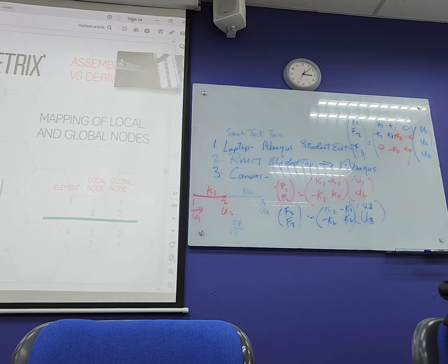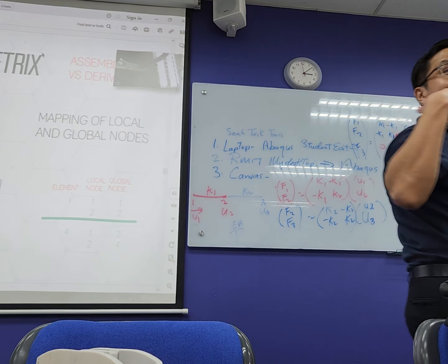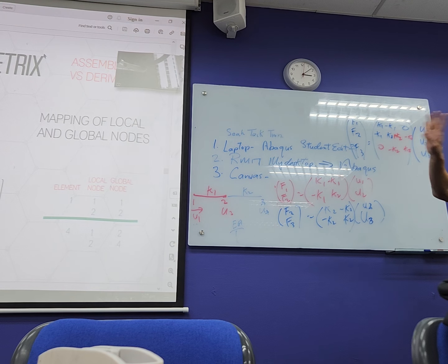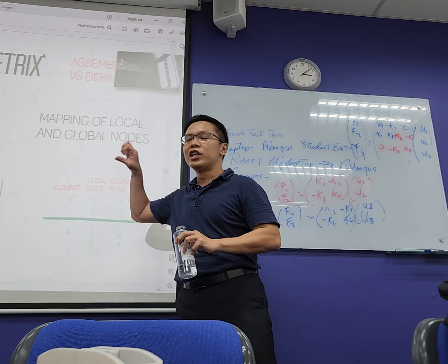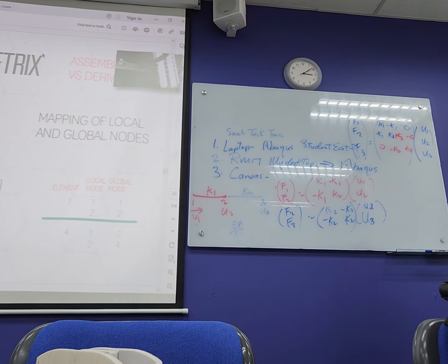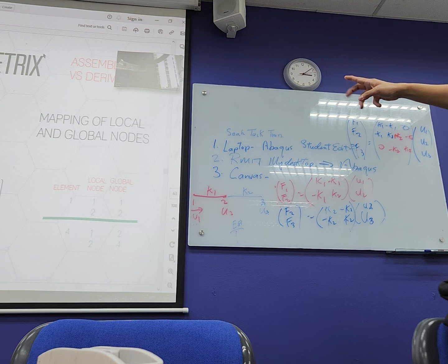Just now we said, as an engineer, what's the first thing you do? Draw the diagram. What diagram are you supposed to draw? You draw the entire model, then you denote each one as U1, U2 for each of your elements. Which is the force, what is the stiffness. Later when you see the assignment, you get what I mean, because this is drawn for you. But this is what you're supposed to draw. Everybody draw this, then write down the standard matrix for each individual element first. And I will get 5 people to come out to draw each element.